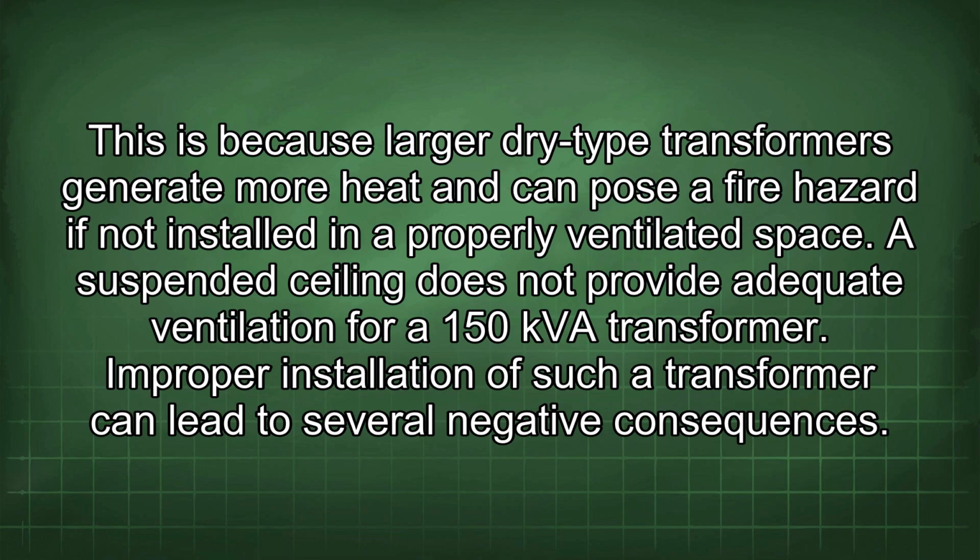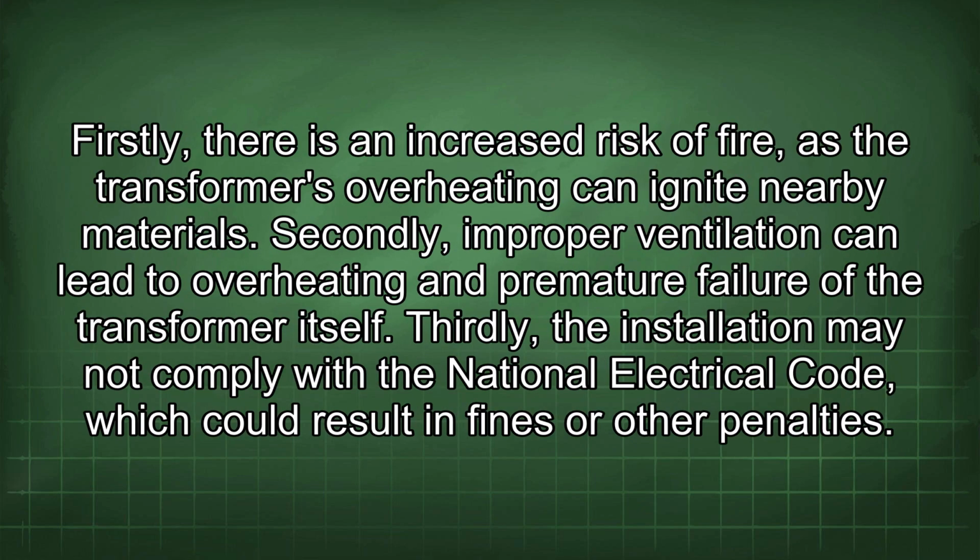Improper installation of such a transformer can lead to several negative consequences. Firstly, there is an increased risk of fire, as the transformer's overheating can ignite nearby materials. Secondly, improper ventilation can lead to overheating and premature failure of the transformer itself. Thirdly, the installation may not comply with the National Electrical Code, which could result in fines or other penalties.